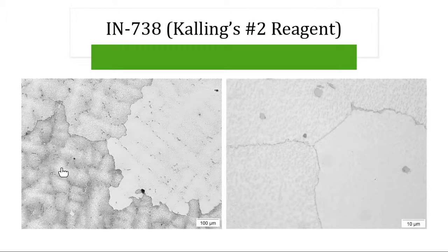That is the inhomogeneous or chemical segregation within that grain as it solidified, giving you this type of coloration and texture. The last portions to solidify are where our carbides are sitting, in the interdendritic spacing of our dendrites.